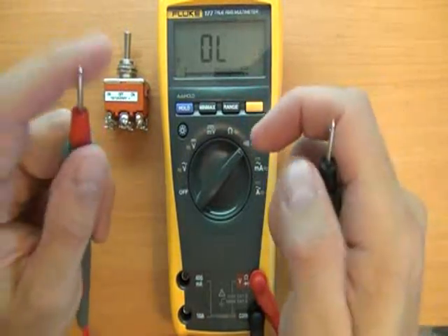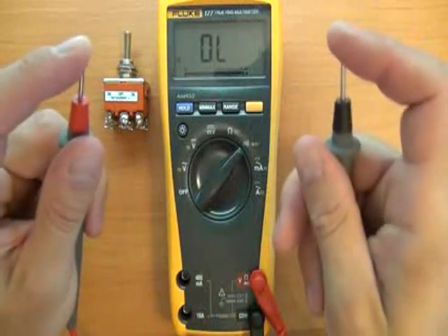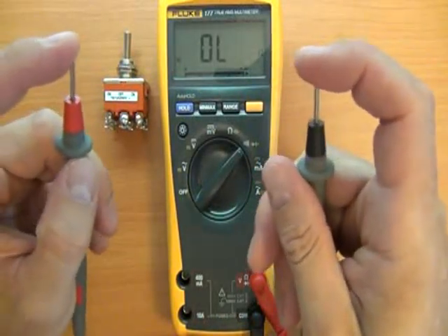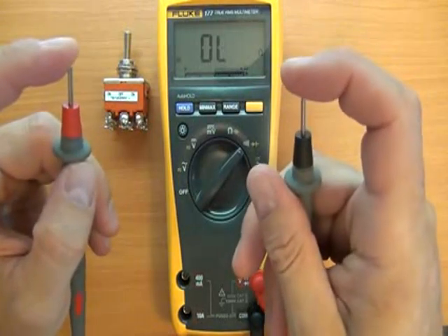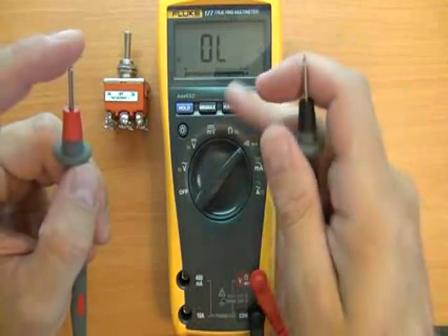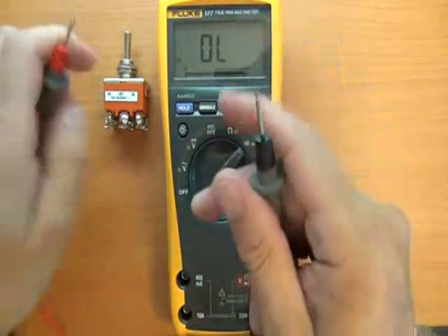But if you've got that piece of electrical wire, you simply place one probe at one end, the other probe at the other, and see whether you get a buzz or whether it's intermittent. Sometimes those can be the worst problems. You get something that works on and off. If you wriggle a wire around, you can then tell, especially if you've got a good continuity tester, whether you've got an intermittent fault or not.